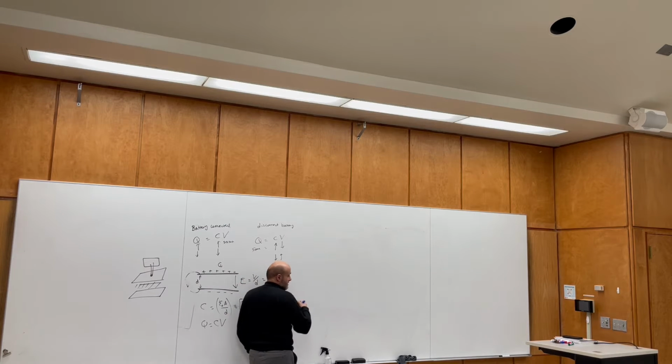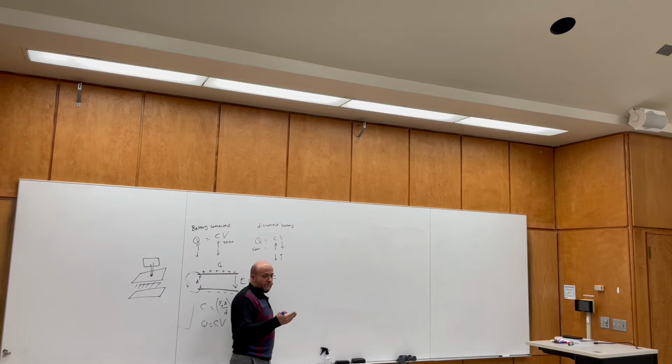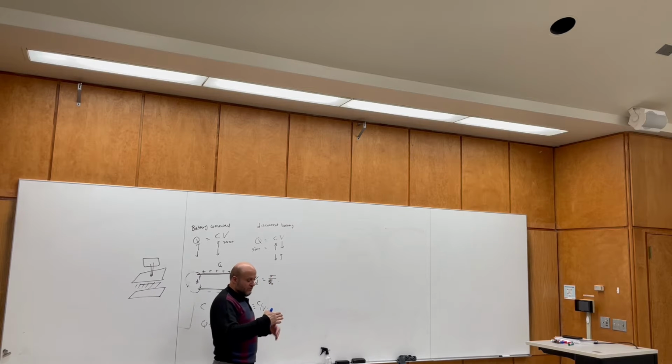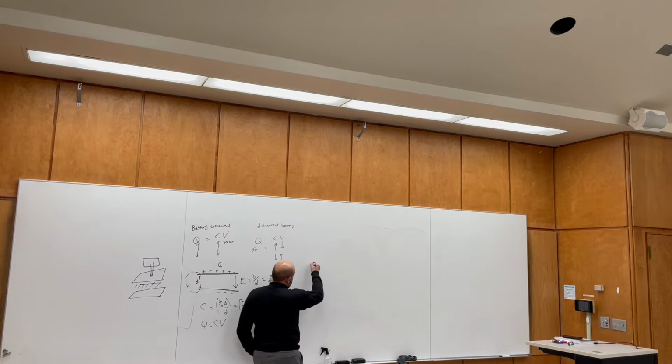Microphone: the sound wave, when you speak, air molecules will be compressed, and then they will be far away from each other, and again compressed. So when you speak in front of a membrane, it is going to vibrate or move. This membrane has a charge. They place charge on this membrane, and it is isolated, so the charge is constant.